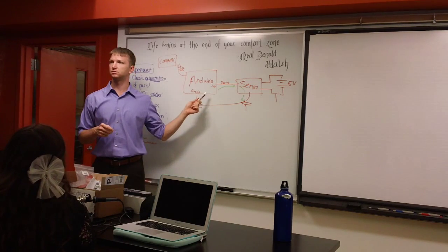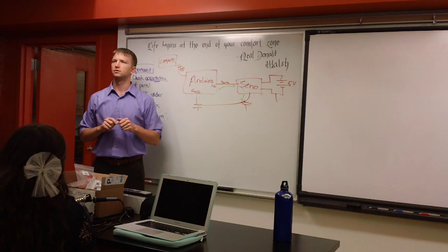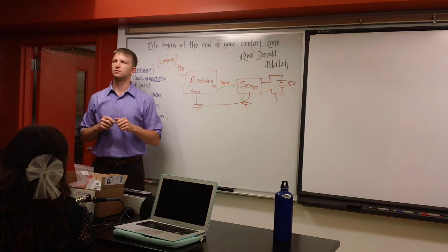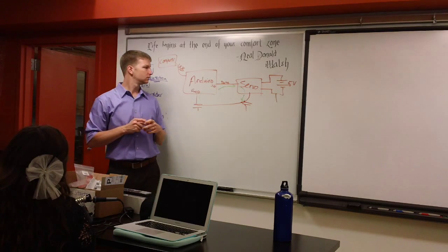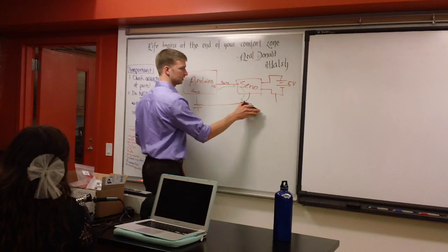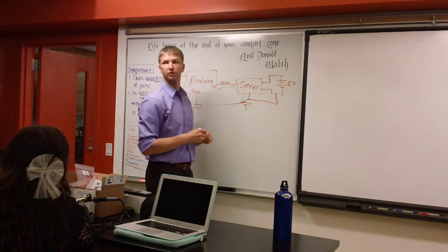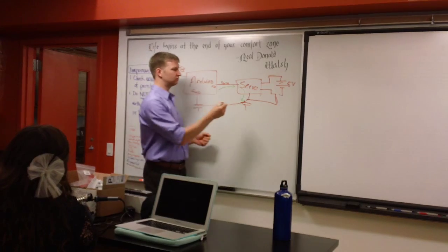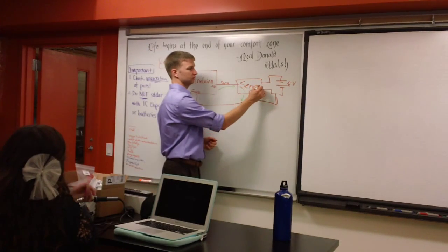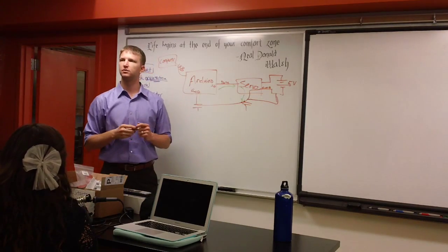Any other questions? Yeah. Would you send it from the Arduino ground to the battery or to the servo? Yeah, I suppose you would take it all the way to here, to this ground. That would be acceptable, because this servo ground here is all the same place.